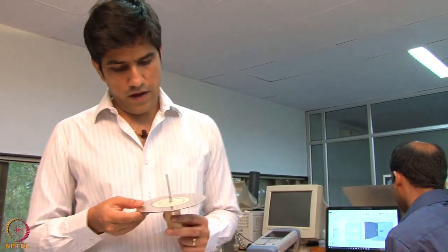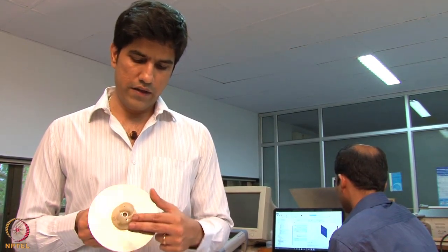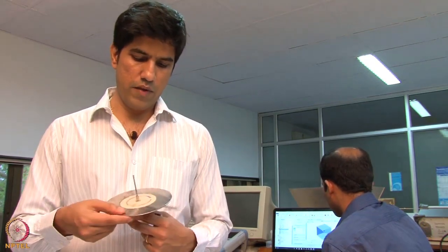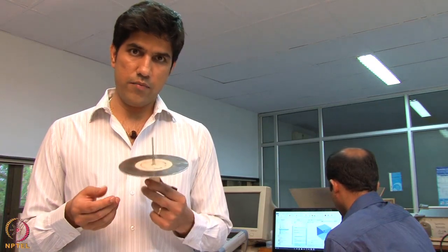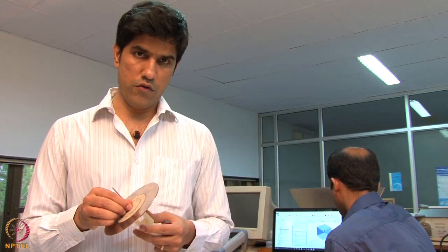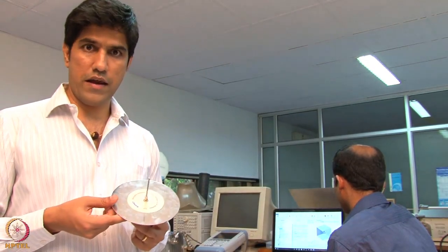The next experiment we are going to do is a monopole antenna. This is the monopole antenna, designed by IIT Bombay. We are going to simulate this antenna, which operates at 1.25 gigahertz, and as you can see it has a coaxial feed and a kind of ground plane. We are going to simulate this particular antenna also using the finite element method. So let's see what my student is going to do and how he is doing this particular model using the finite element method.